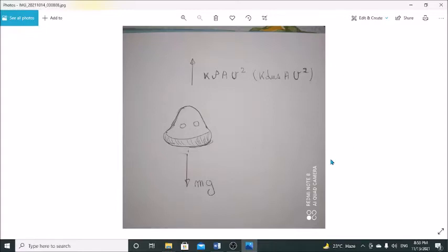Now here let us study the forces acting on a falling body. The only two forces acting on a falling body are the weight downwards, mass times g, the acceleration of gravity, whatever the value of g, could it be zero at very high distances, and the resistance due to air, which is equal to k, rho density, a projected area, v square, the square of the velocity.